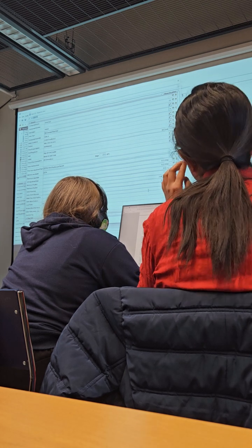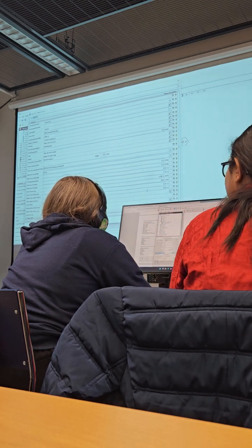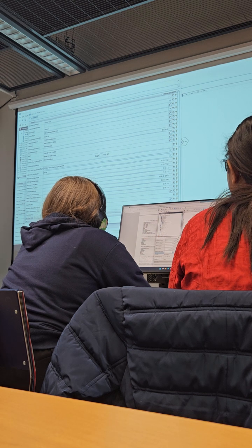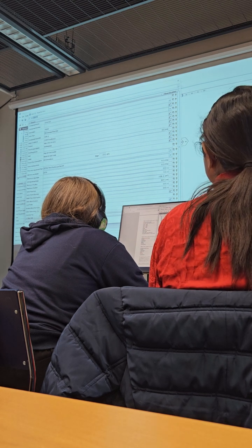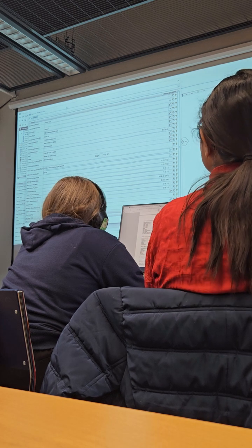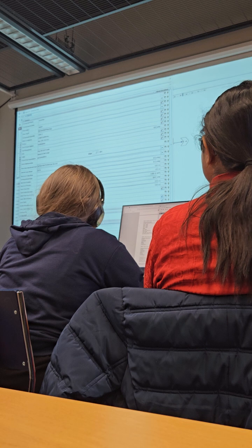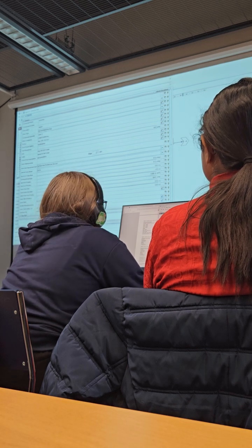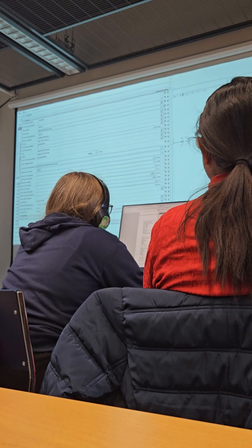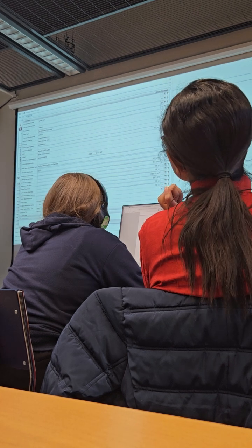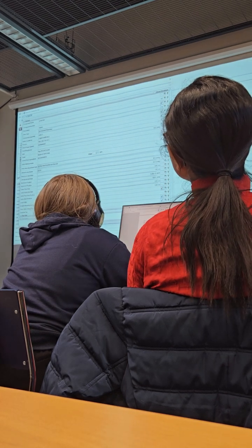So here it is important that you fill all the things which are red, and then you can continue. Here is a thing that you can do now, because the valve type here is considered as a constant flow area type of valve. So it is just a valve which doesn't move at all.